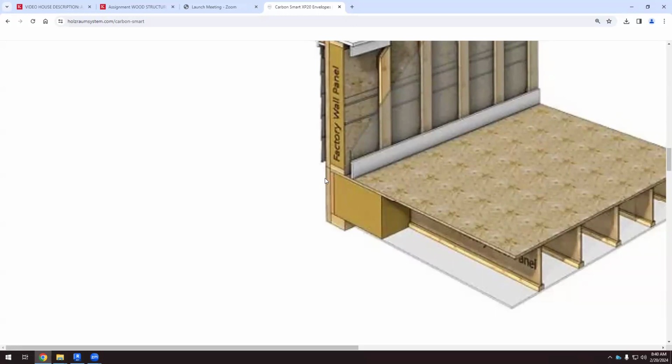We can have some infiltration, but if we have this with the fiberboard or the cellulose, that would be harmful for the material. So that's why we need the first layer, a couple of inches or 3 inches, I don't know how much, or 4, I don't remember how many I used here. And then that protects the internal thermal insulation. So the bulk of the thermal insulation, most of the material, is here, but it's indoors, protected from water leaks or infiltration that we can have from outdoors.